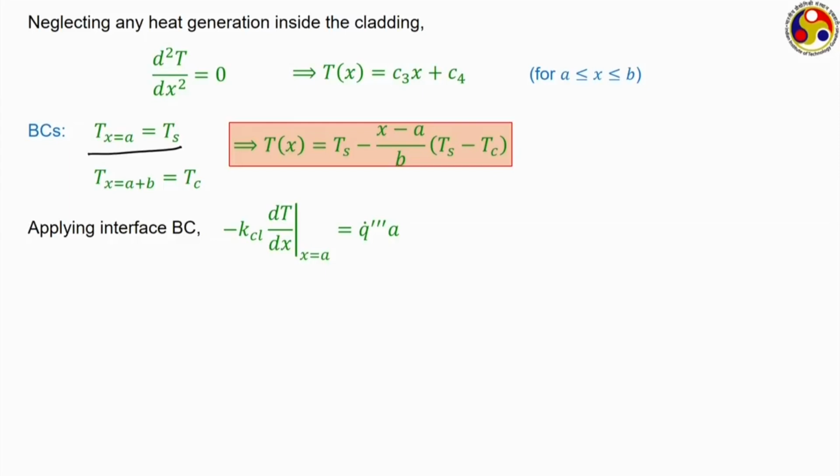Here we have used Fourier's law of heat conduction, and the heat flux that is coming out through one of the phases. Let me write it in a better way. The heat flux coming out of one of the phases should be equal to the energy produced in that half of the reactor, that is, as we have seen in the previous slide, q dot divided by the cross section area. That is why we are having this term here.